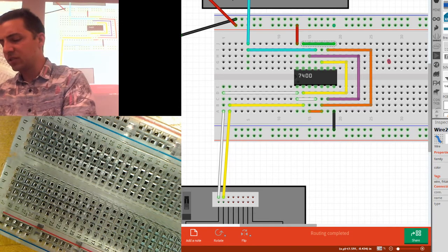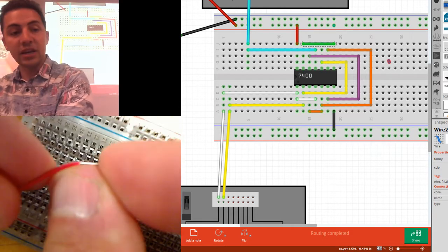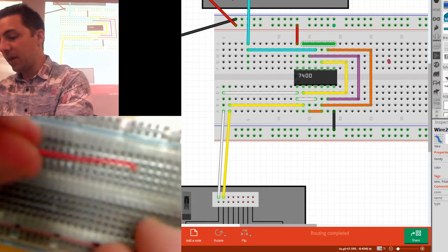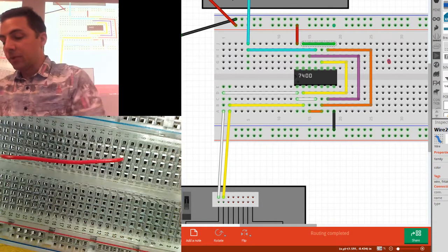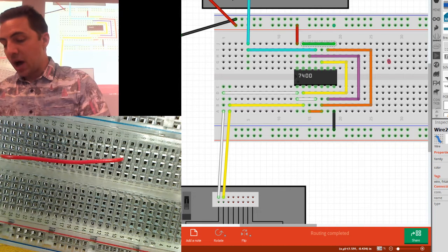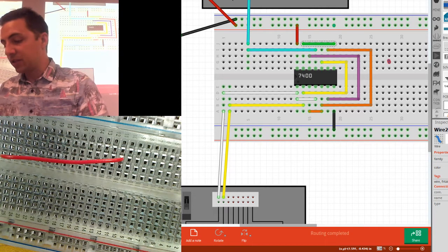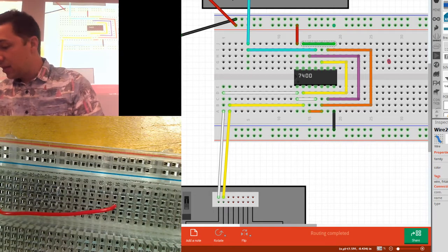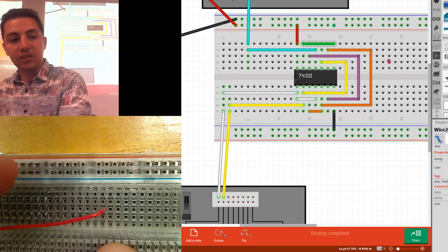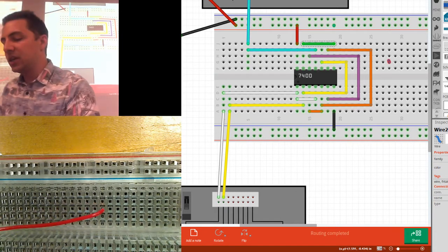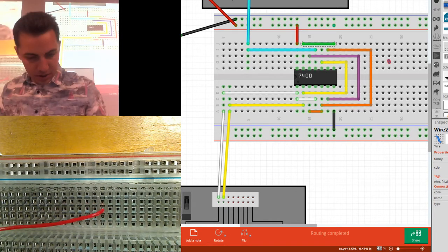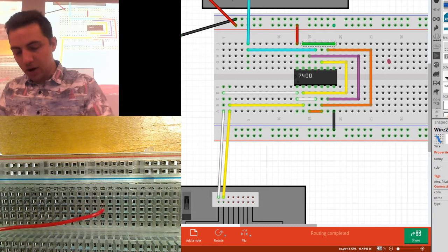At that point, though, it's just a matter of bending your leads into a U shape and then sticking them in a breadboard. So that works well for medium-sized wires. For short wires, though, specifically the kind that I want to go from, say, the ground rail to a single pin, it's actually easier. Let me get a black wire here.